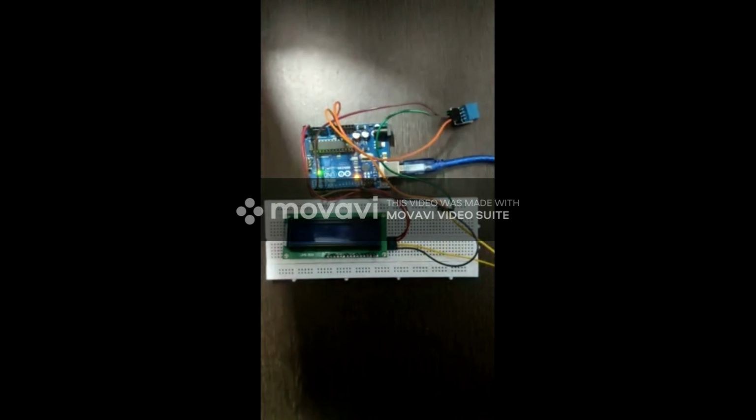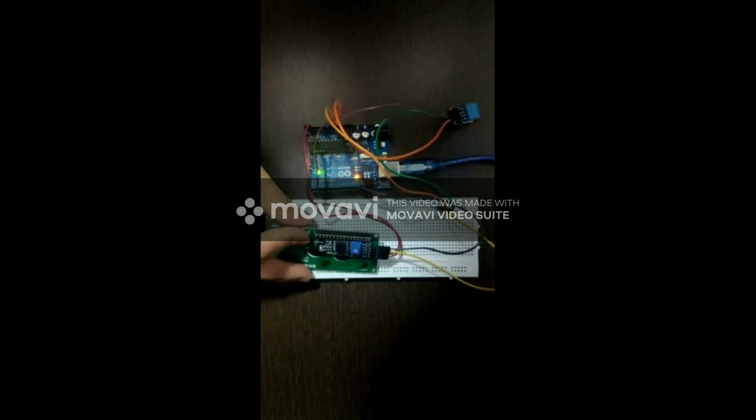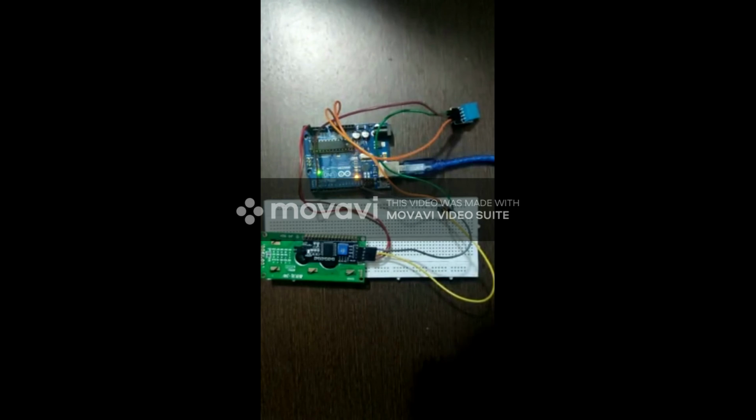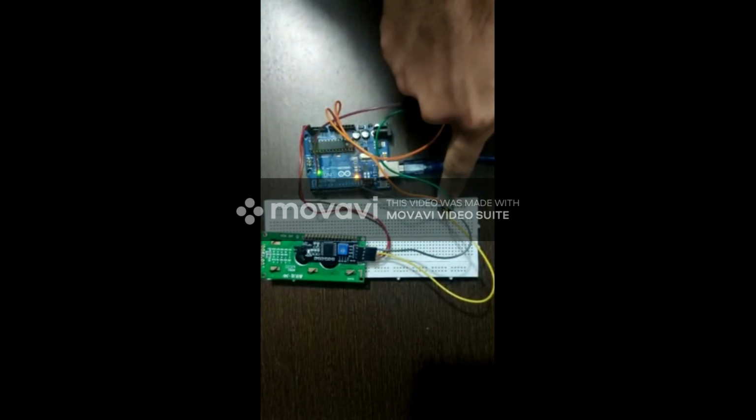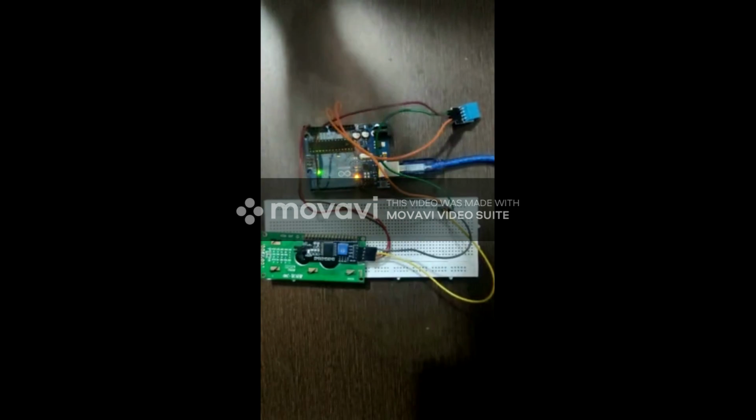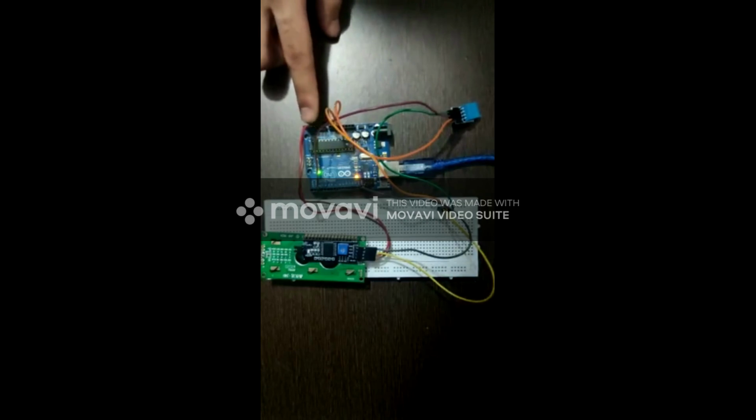After that, we have 4 more connections with the I2C module that has been soldered together with the LCD display. These connections are as follows: GND pin of the I2C module to the GND point on Arduino, and VCC pin of the I2C module to the point on the breadboard that is right next to the 5V pin, that is this yellow colored wire that is connected right next to the 5V pin connection on the breadboard. And after that, we have 2 more connections, that is SDA and SCL of the I2C module to the A5 and A4 points on the Arduino here, that is right on this brown wire.